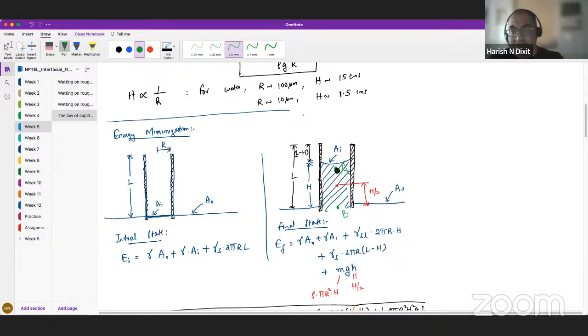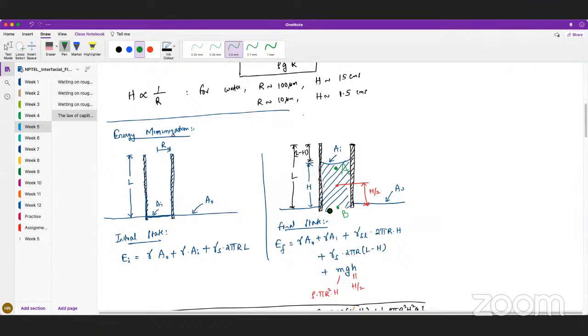No. The mass balance says that whatever rate at which fluid is entering at B is the same. You shouldn't be strictly applying this idea of the fully developed velocity profile here, right below the meniscus. The fully developed profile is applied in an average sense. Okay, that's the first one. Otherwise, you should expect a bulge in the middle, not a depression. Yes, sir. So even if we consider it in an average sense, the velocity would be the same in an average sense. So dynamic pressure.